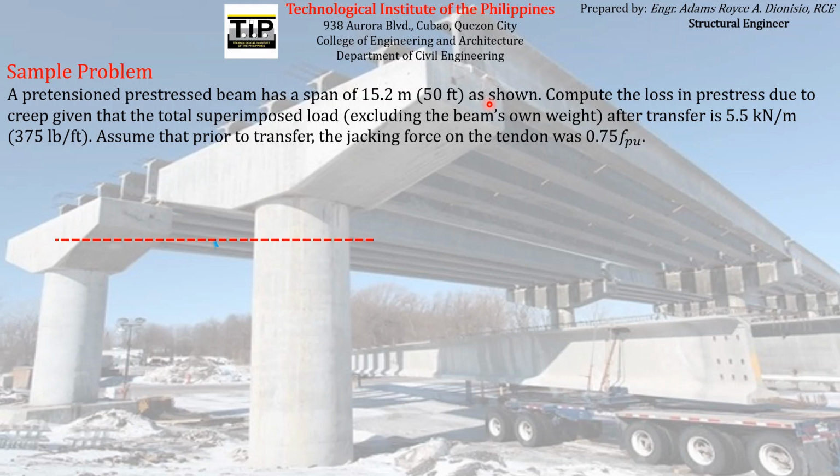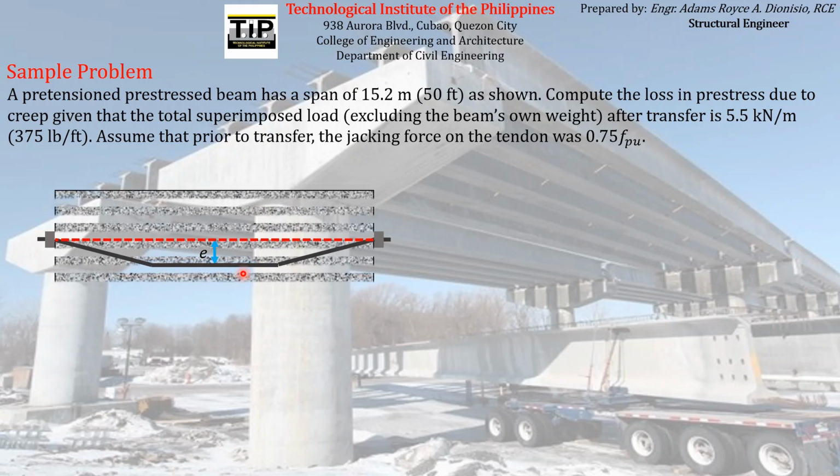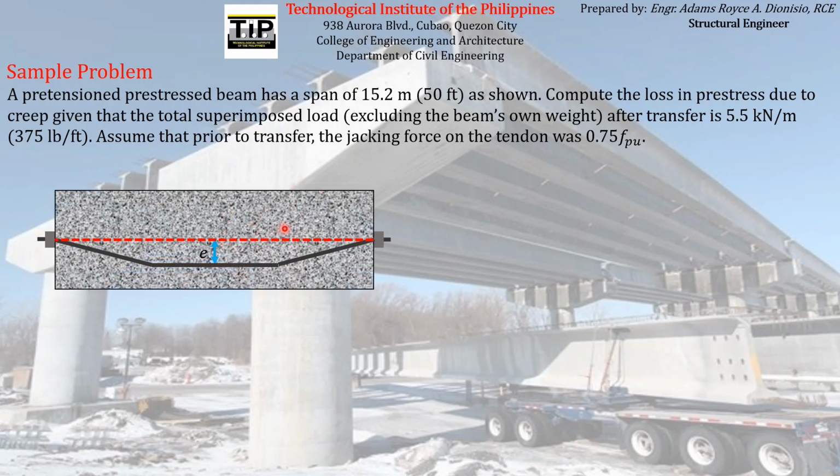So this is the pre-stress beam with a tendon profile similar to this, which is actually a harp tendon, usually used for pretensioning as mentioned on the problem. And again, this is the pre-stress beam, which is actually a simply supported beam, which supports a uniformly distributed load W.